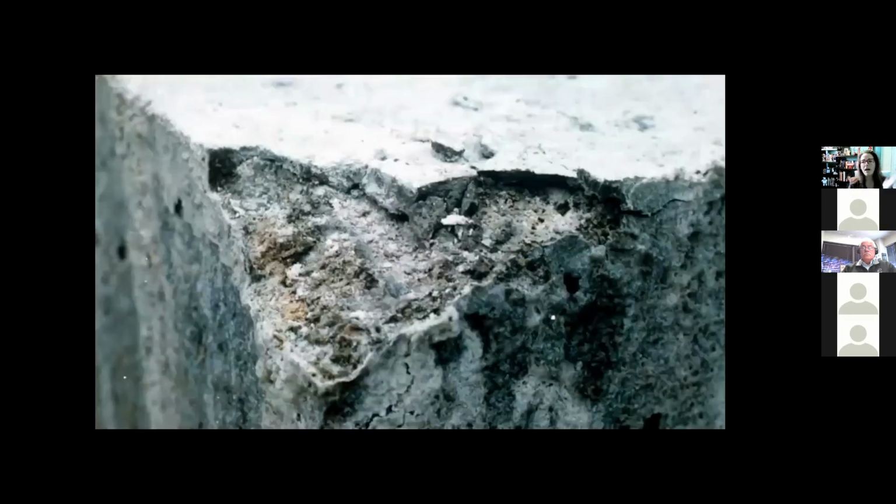What would I do with these spalls? I would do patch repairs. So on this edge joint, we'd be removing the material and making sure it's a proper edge if necessary for that structure. If it's a driveway, you might live with it. But if it's an interior industrial floor slab, you're gonna fix that. But you want to fix it with high quality, and you might even be reinforcing that edge, whether it's a steel plate or rubber plate. There's different things you can use for load transfer.